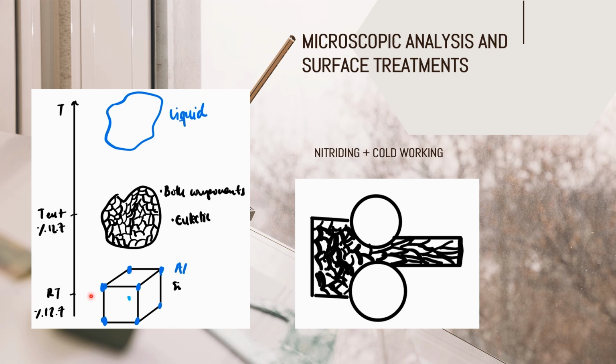We will start with a crystalline structure in which we only have that alpha plus silicon stage. The aluminum is represented in the edges in a BCC structure. That may be another one, but I decided to choose this one. It could also be a simple cube or an FCC depending on the material. And the silicon, which is the rest of the material.